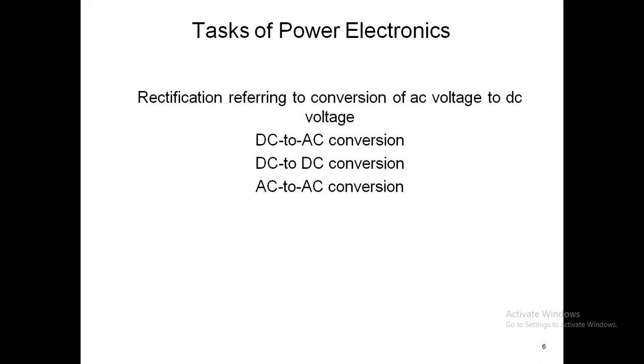If you go through the course structure, then you have to analyze these waveforms, like input current, output current, input voltage, output voltage, switch current, switch voltage, all those. Every element inside the converter, you have to analyze its current and voltage also. By analysis, you will find some critical condition on which the converter will be working. So you have to find out all those element values also, and there will be some kind of design also.